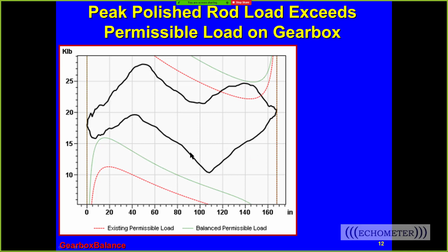And so here on the downstroke, it's not going below the red line. And if we balance it by putting the weights in the correct place, then it won't be overloaded on the upstroke or on the downstroke. See how the counterbalance moment comes up on the downstroke, and you have to be concerned about overload on the downstroke if you move the weights out farther on the upstroke. So this is saying that we'll be okay if we counterbalance it so we don't overload right there, and we didn't overload now on the downstroke. It comes up, but it didn't overload. It didn't cross that line.